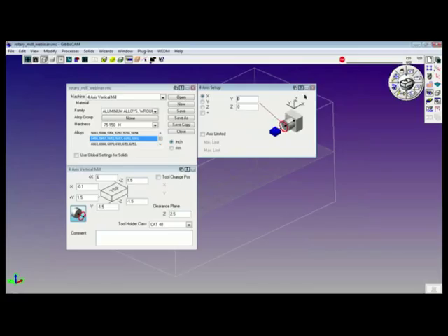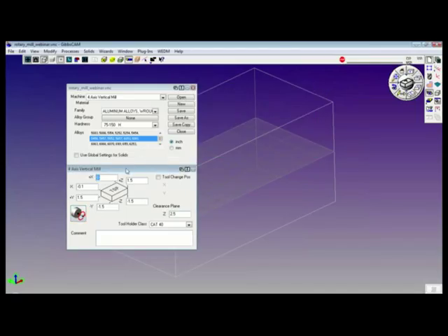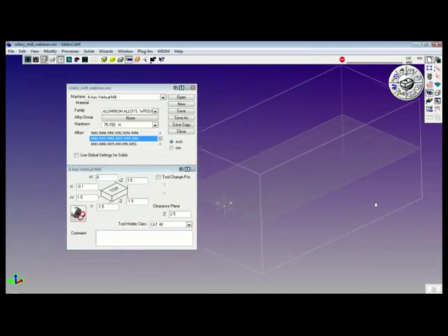I'm going to go ahead and close this fourth axis dialog up. We've set it correctly. We set the conditions correctly. The stock definition is based on how the part will lay on the machine. I'm just starting with an X value of 6 inches, making my X 0 on the left side of the part.